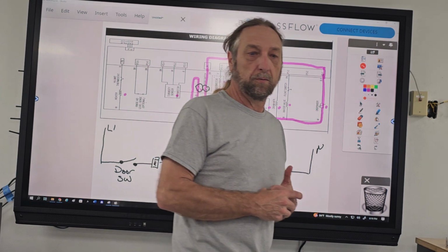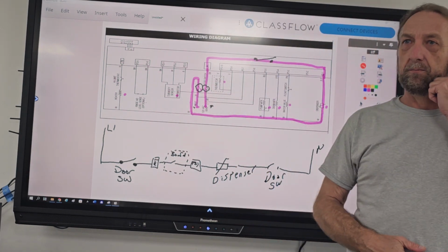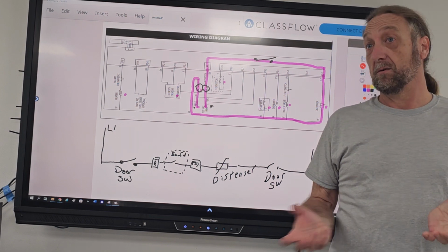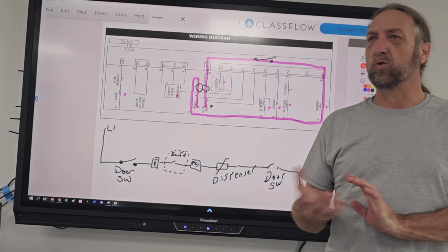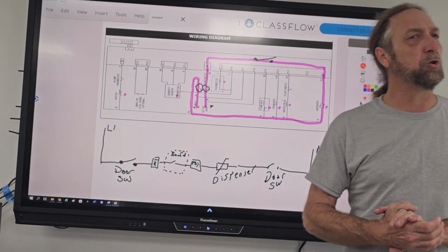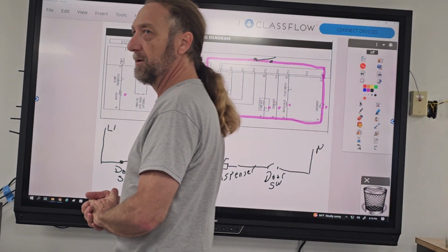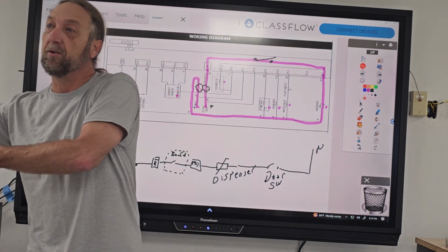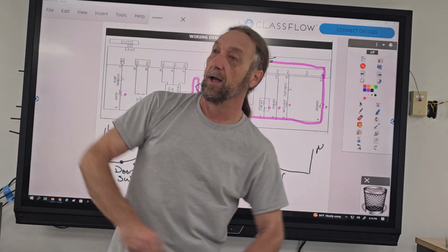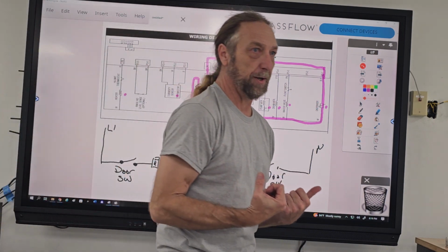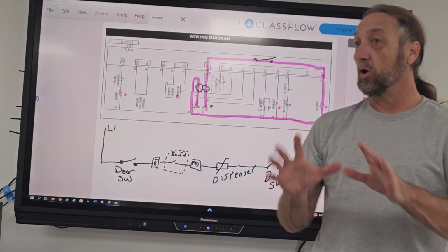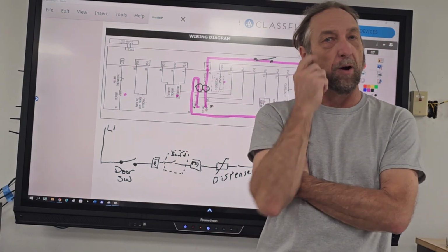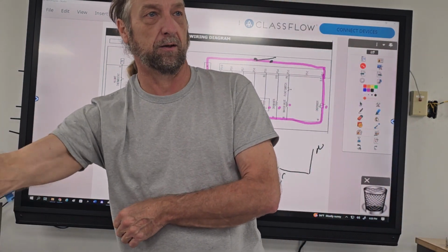The dispenser doesn't come out, but you press start and you hear water coming in. Oh, water's coming in, huh? How about you hear the drain pump run? What's the first thing you usually hear when you turn on the dishwasher? The drain pump. The drain pump usually comes on first because the cycle previously might have left a little bit of residual water. We want to try to pump that out before we put fresh water in. So let's assume the drain pump is running. You press start and you hear the drain pump running and you hear a little bit of water shoot into the sink and the garbage disposal.